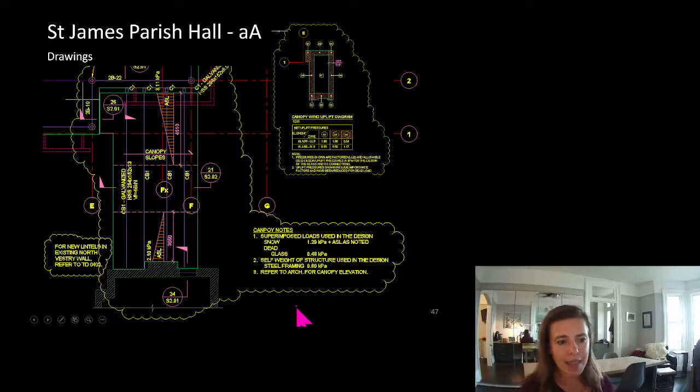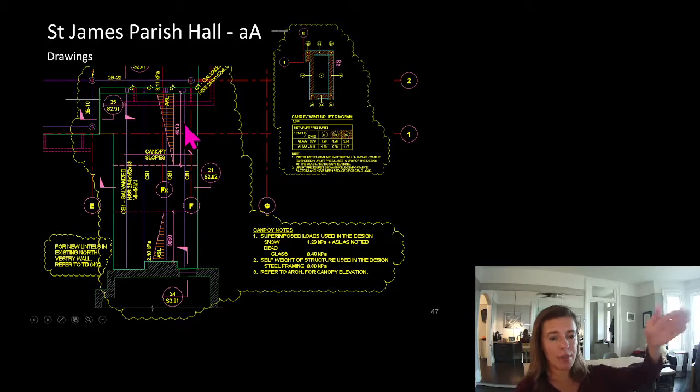All right, I think this is the last canopy that I'm going to talk about before Dave jumps in and goes through some images. This is another old one. It's one with Architects Alliance that I did in, I want to say, 2008, 2009. And this is a glass canopy, but what's really interesting about this one is we had a major structure supported on two ends, but at this end, it was supported on an existing heritage building. And at this end, the members came and cranked down and supported on steel below.